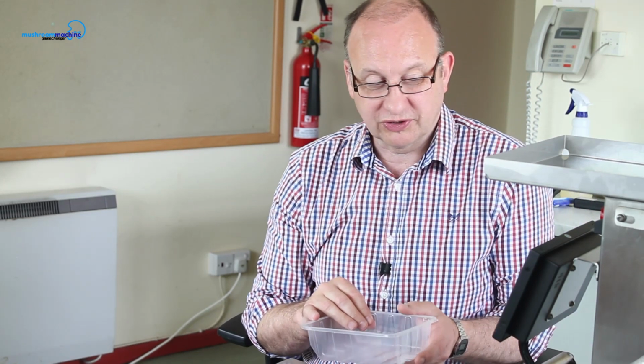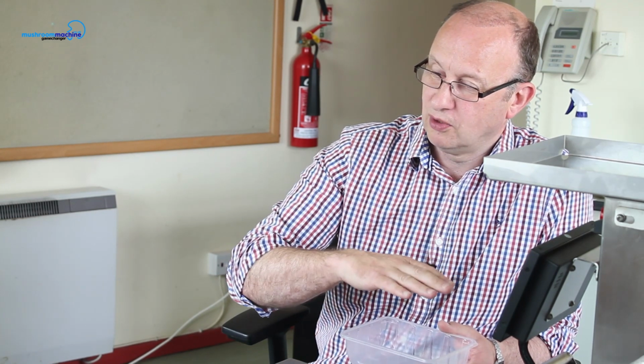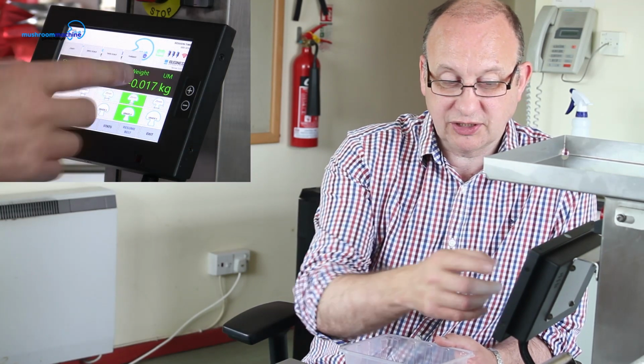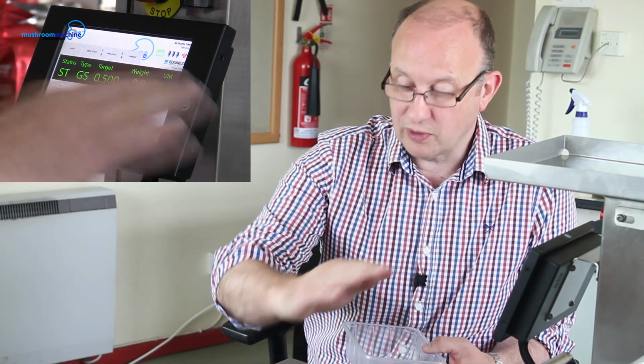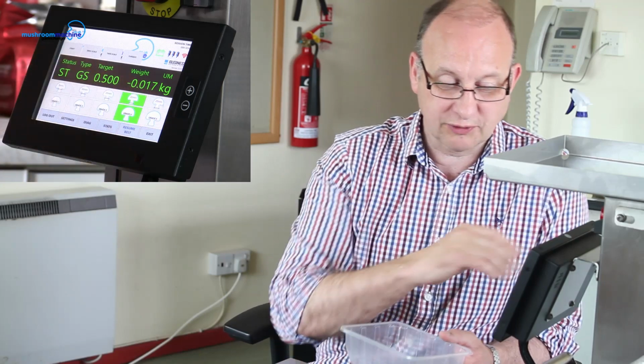But what we found, and again we had to change it, was that with longer stalks, so if I had an extra 7 mil on my stalk, as I was coming up near the top of the punnets, it was starting to push down into the punnets or the mushrooms below it. So what we did was we then said we can actually change the stalk. So the pickup doesn't alter as this here, but when you're putting it in on the weighing pan and into the punnet, it doesn't go as far down on the 2nd and 3rd rows. So that's what that's for there.